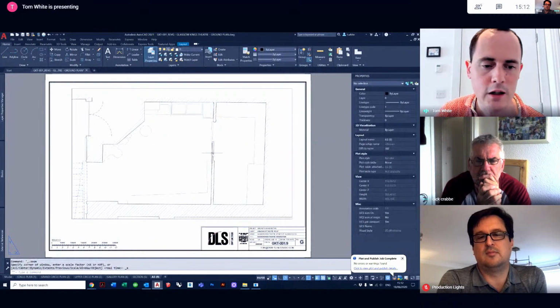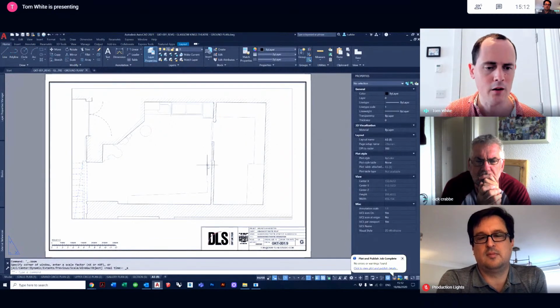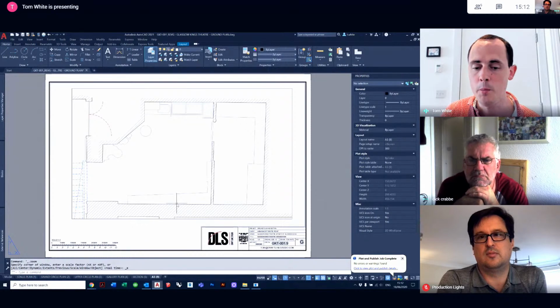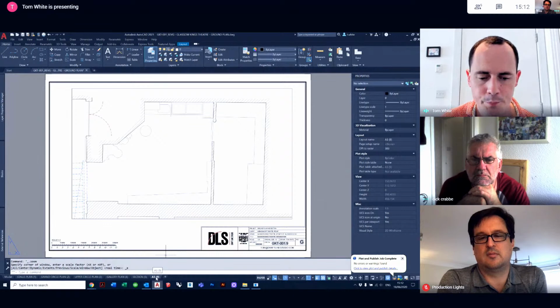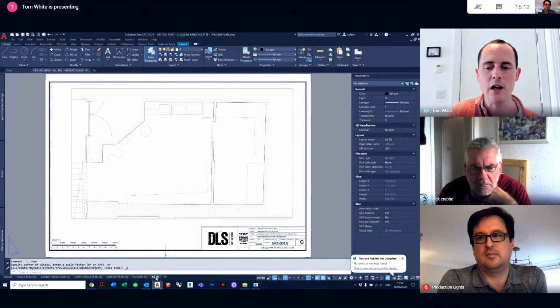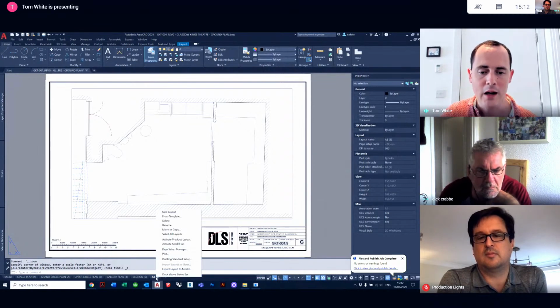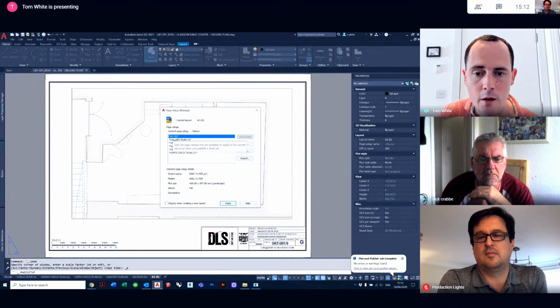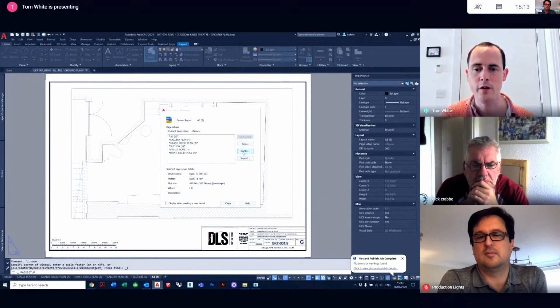So I sent this off to Dick and Dom, and they said, oh, hang on a minute, I need it on a different size piece of paper. That's fine. In this circumstance, they desire to print it on a plotter, and they desire to print it in A1 size. So what I do now is, my tab down here, which is called A3 in brackets 9, is the layout we're seeing on an A3 piece of paper. I'm going to right click on there, and I'm going to do Page Setup Manager. I'm going to edit this A3 in brackets 9 by clicking Modify.